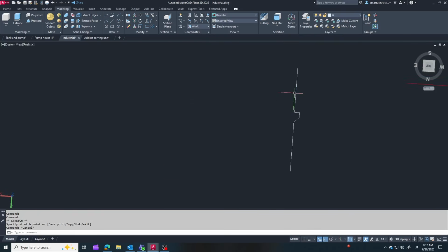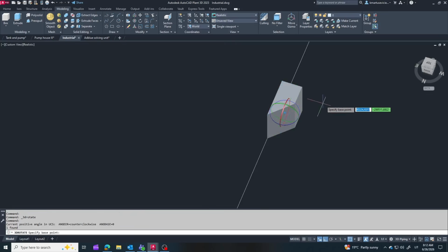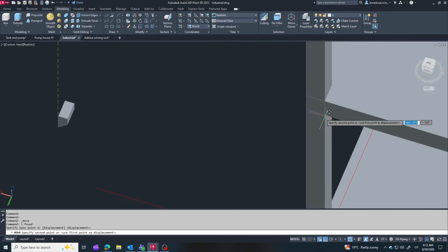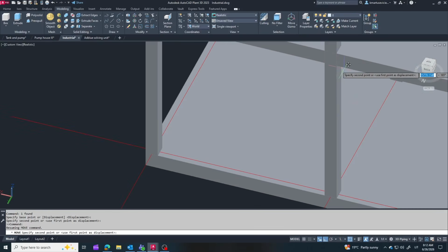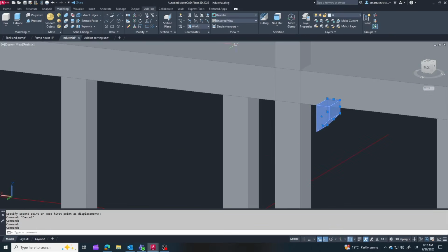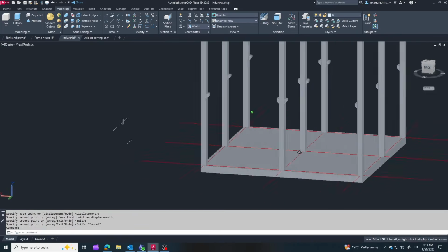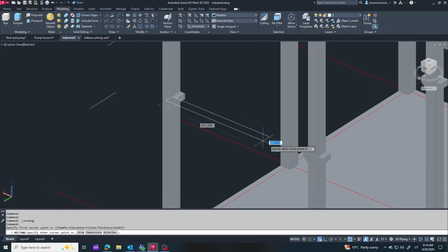Instead of designing piping in empty space, we'll work inside a realistic industrial building, just like in an actual engineering project. I've already created the grid and marked all floor levels, so let's continue by detailing the concrete structure. I'll start by adding the column corbels that support the concrete beams. This will help you understand how precast concrete buildings are assembled and, more importantly, how the building structure affects pipe routing.